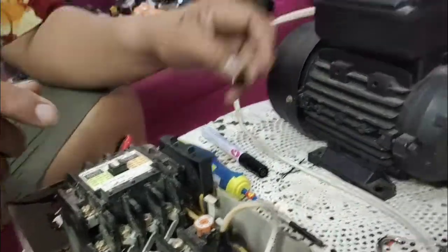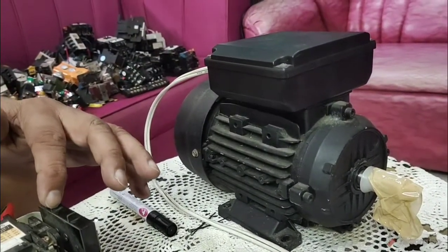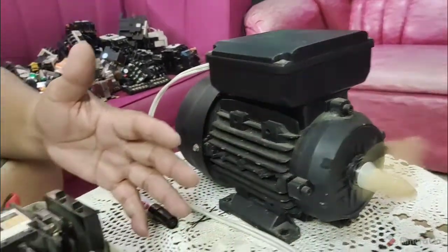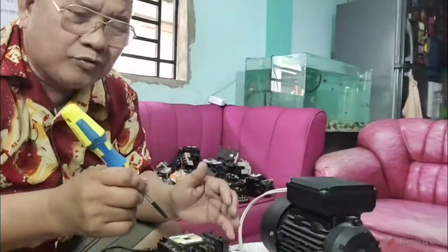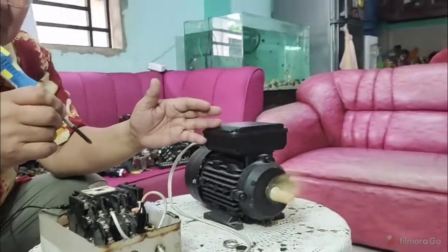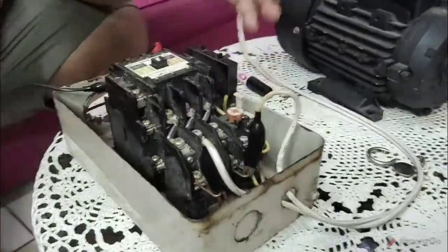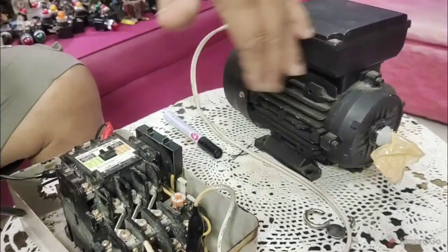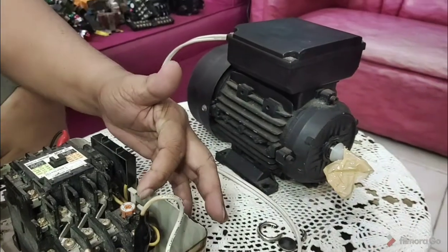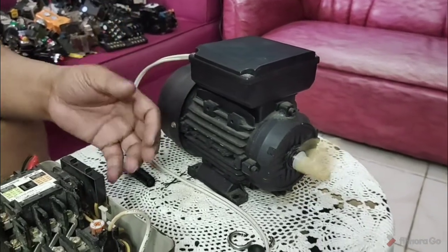Now, whenever there is what we call a short circuit here or overload, it will only trip. Now there is no trouble. But what if the trouble is there, no? Too much load in the circuit or too much load in the motor. So you load the motor beyond its capacity. So it is now the protection, the overload relay, that will take responsibility. So look at this. See? It's off immediately. Meaning to say there is an overload. So what you will do? Maybe you remove some loads and then reset like that. When you reset, then it is on again. Okay? So that is the magnetic starter.